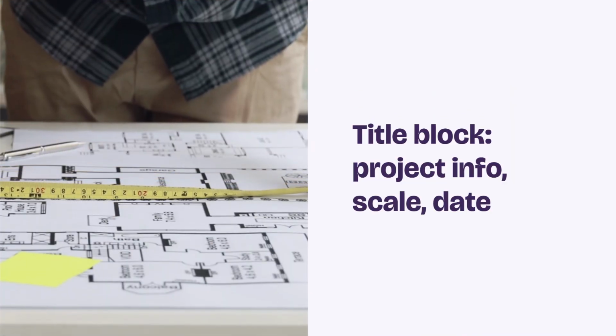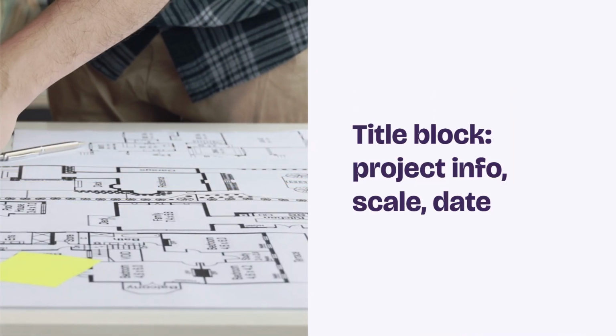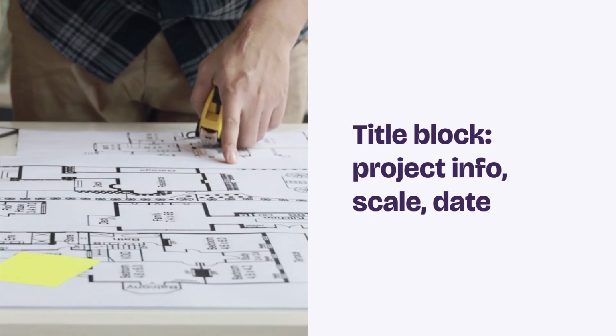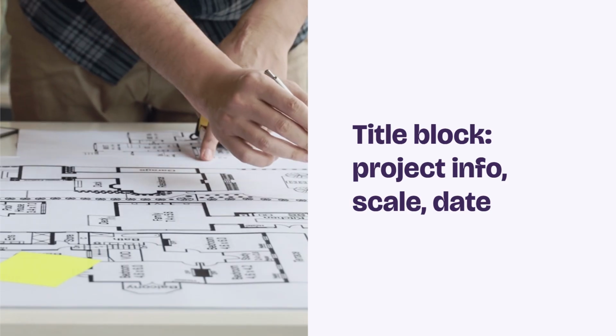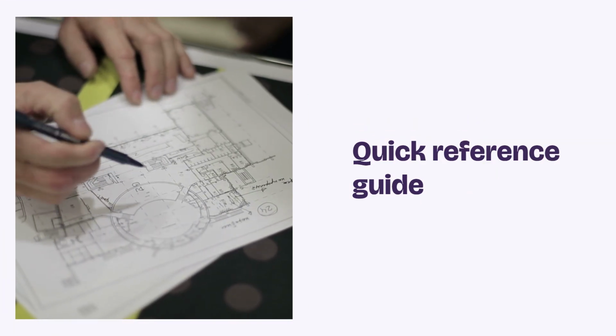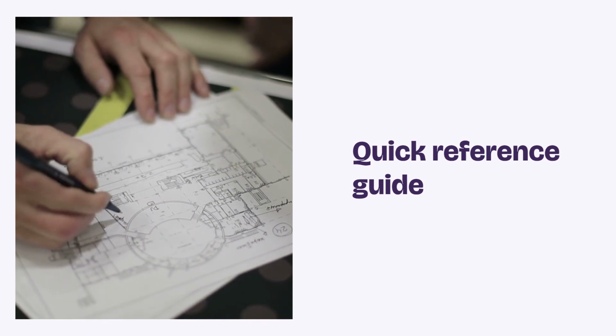Now, every plan starts with a title block, usually found in the corner. Here, you'll find the project name, the drawing scale, the date, sheet number, and who prepared it. Treat the title block like your plan's table of contents. It's your quick reference guide.